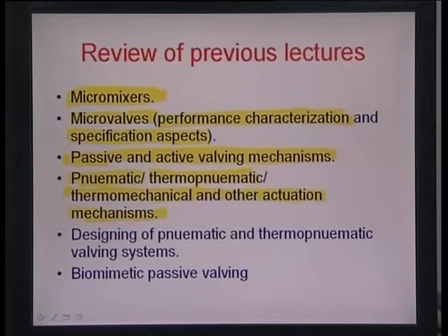We also tried designing some of these pneumatic and thermopneumatic valving systems and saw that the designs have to be made in a manner which fits the micro scale, making an area ratio between the inlet and the valve seat so that the amount of force needed for actuating the valve member is small.